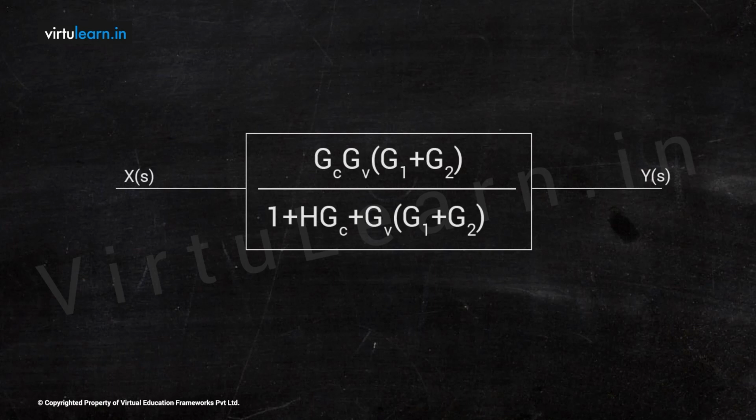That means the output of G3 is given back to the input of G2, which is interconnected between these two loops. So whenever you have this kind of problem, we need to look at how many summing points there are, what the internal summing points are, and how to reduce them using the available block diagram rules.